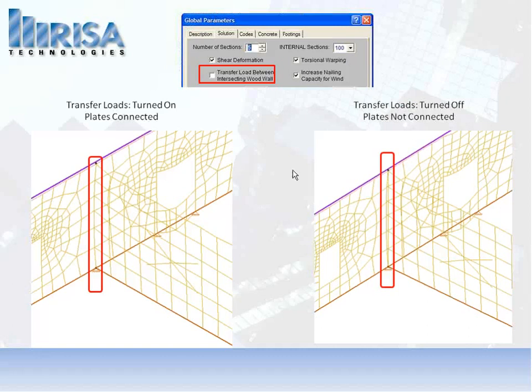And this is the type of question you want to ask yourself, and you can see I actually have a rigid diaphragm in this model that I'm looking at here. But rigid or flexible, those types of things. What do I want to be connected, and do I want them, if they intersect, to be connected automatically for me? That's a checkbox you can give it there.